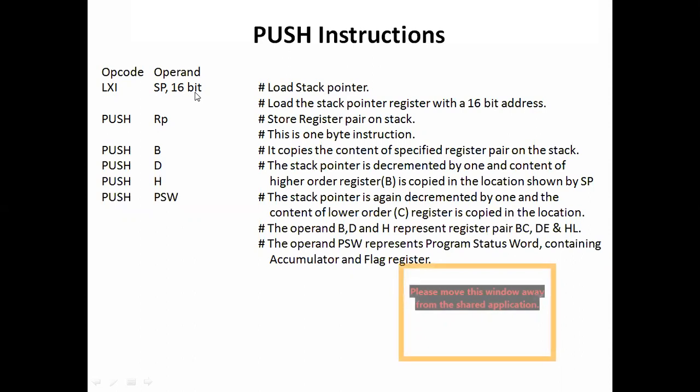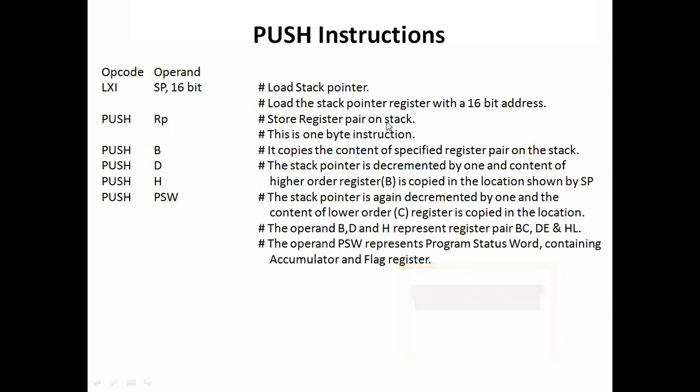It will be loading the stack pointer register with a 16-bit address. And then we will be using the push instruction. The format of the push instruction is push RP, where RP represents the register pair. So push RP means store the register pair on the stack.